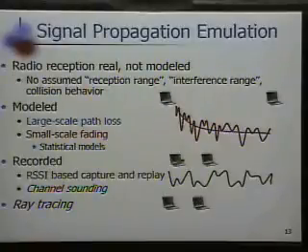All right. And another thing you can do is use a channel sounder to get very fine-grained detail recording the channel. The RSSI doesn't include full multipath information. A channel sounder can capture that, and if you have one of those devices, we could use it in the emulator. I haven't done that. The other approach that... Go ahead.